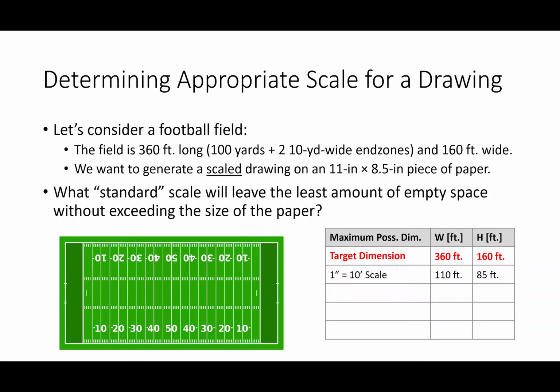So does a 1 inch to 10 foot scale make sense? No. What about 1 inch equals 20 feet? Does that make sense? No, it doesn't. Now, what about 1 inch equals 30 feet? If I do the math, could I fit the football field on the sheet from a height perspective? Yeah, I could. The height on the sheet is 255 feet. So I could fit 255 feet of height on that sheet of paper, and the football field's only 160 feet tall. So I can do that, but it's too long.